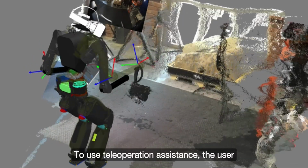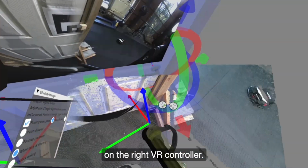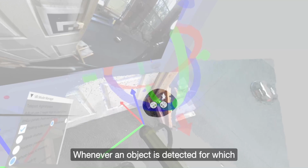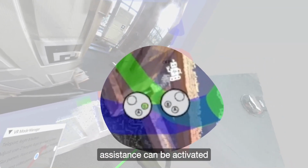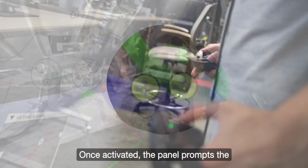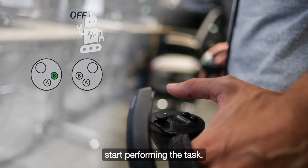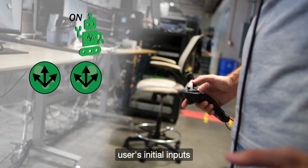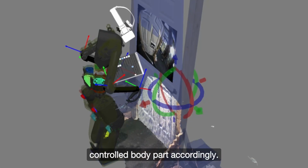To use teleoperation assistance, the user can refer to an information panel displayed on the right VR controller. Whenever an object is detected for which the assistance is available, this panel informs the user that the assistance can be activated by pressing a dedicated button on the left controller. Once activated, the panel prompts the user to move and start performing the task. This allows the robot to analyze the user's initial inputs and determine trajectories for each controlled body part accordingly.